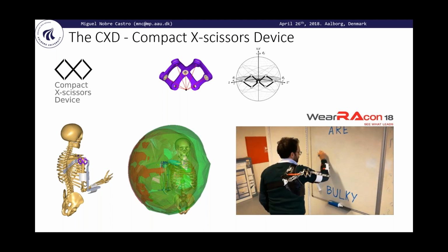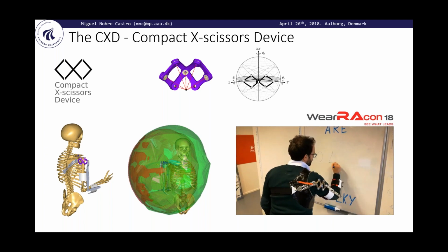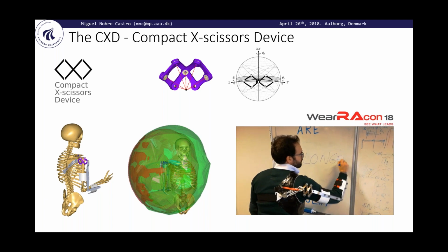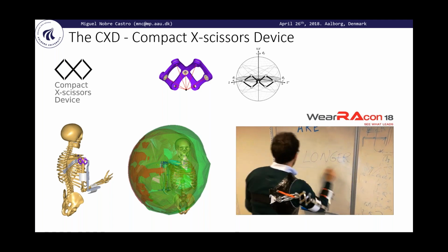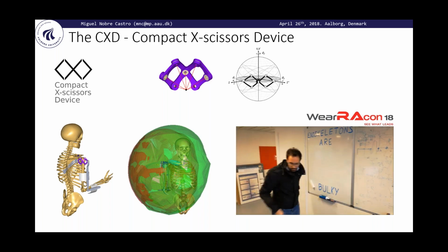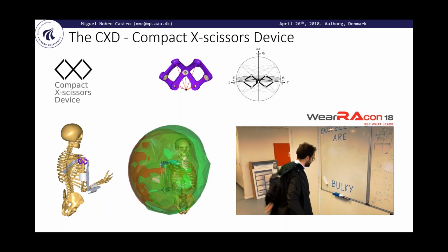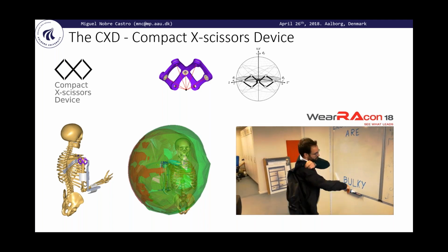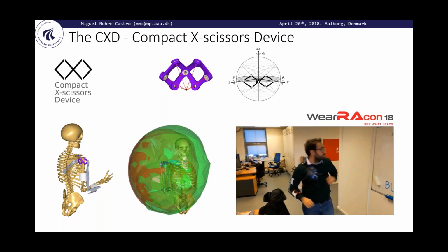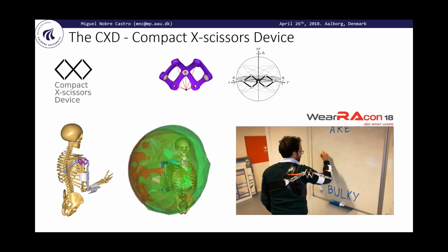So the one you're seeing there on your right side, this very compact solution, shoulder mechanism, we by far only manufactured one mechanism, and that was possible because we performed some kinematic simulations within the AnyBody Modeling System. And as you can see here, now you're familiarized with these clouds, these shapes of the reachable workspace.